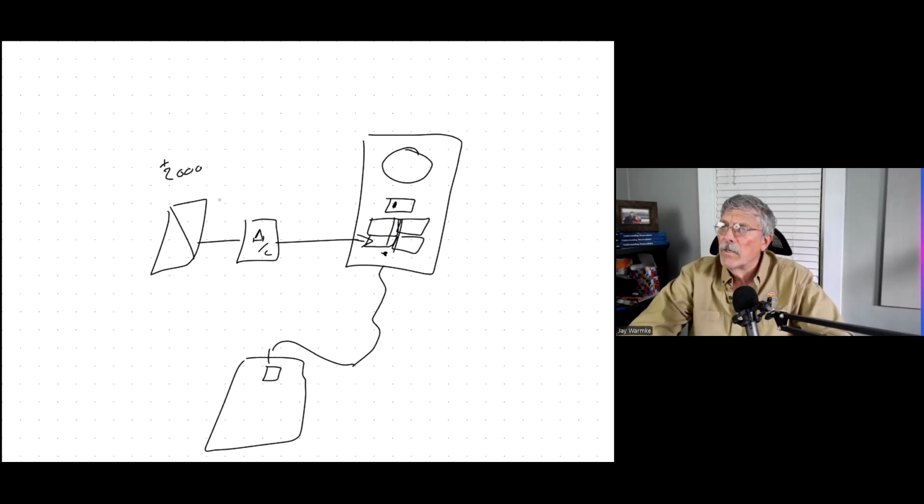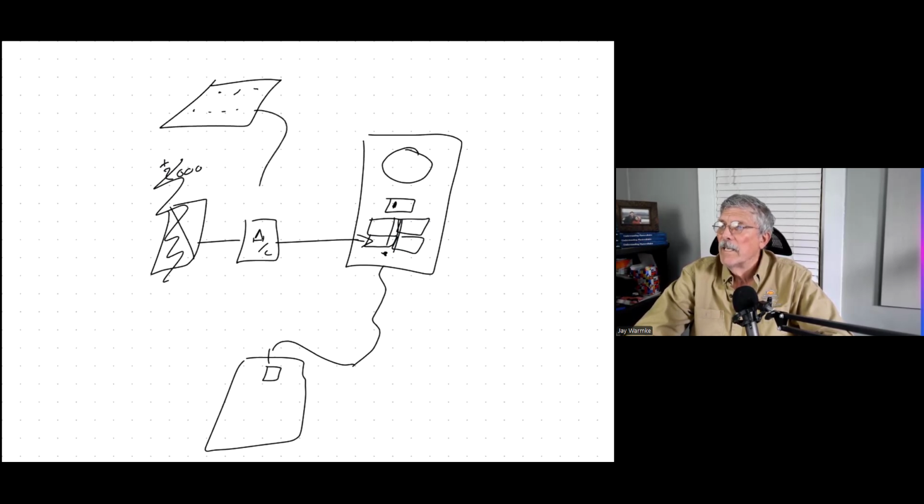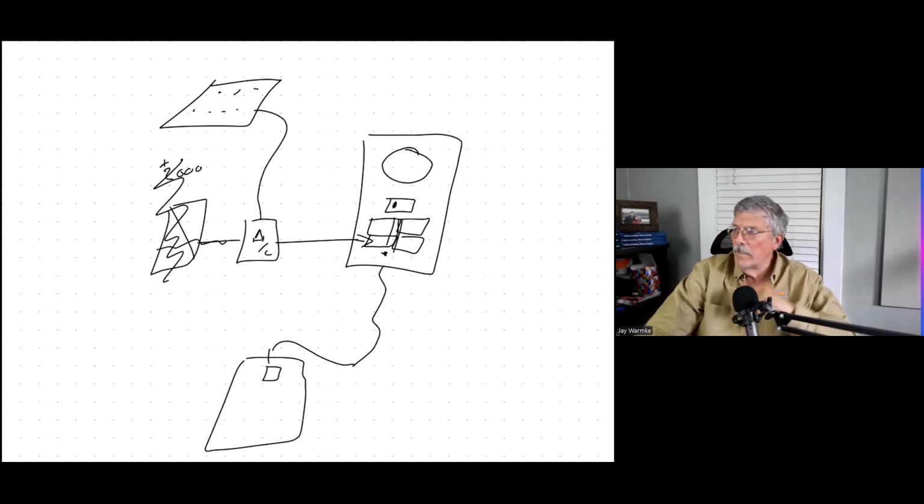For a microinverter system, this is a really super idea, because your microinverters are going to be attached up here on your array on the roof, and then you're just going to come down to your AC disconnect and hook straight in there. So there's nothing really for anyone to steal in that system. So it's a really lovely place to make your connection.